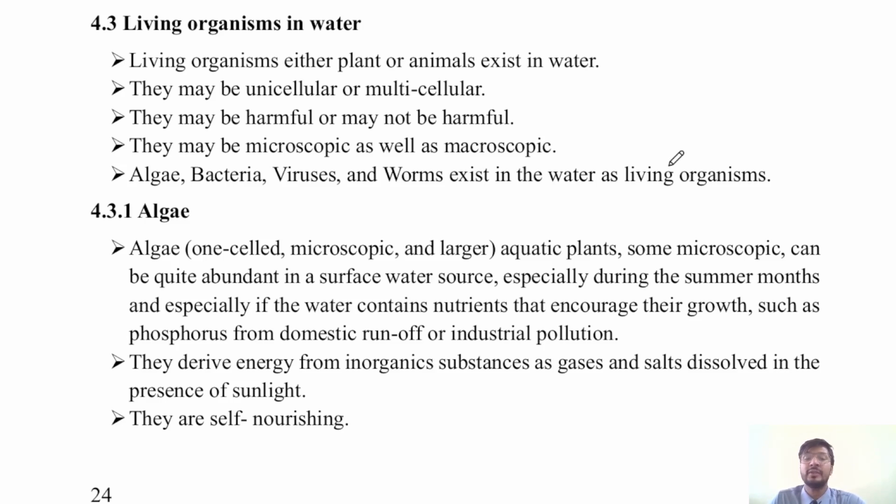Excessive algae growth can cause problems such as taste and odor issues in water, clogging of filters in water treatment plants, and formation of nuisance slime growths on intake pipes and equipment. Algae can be controlled using chemicals like copper sulfate or chlorine.